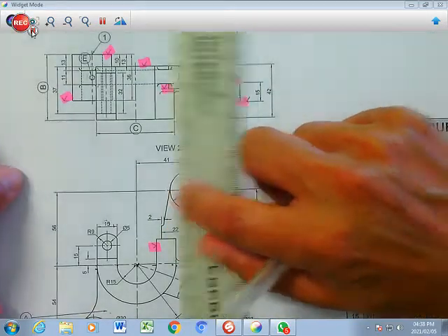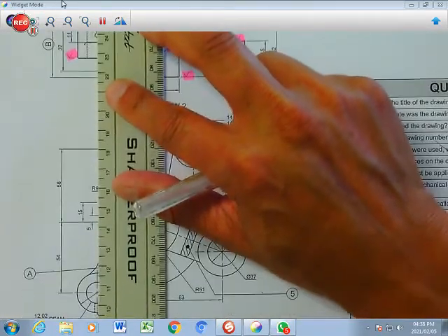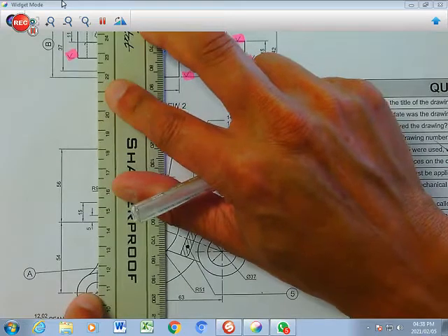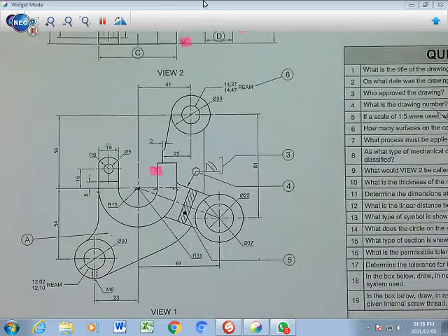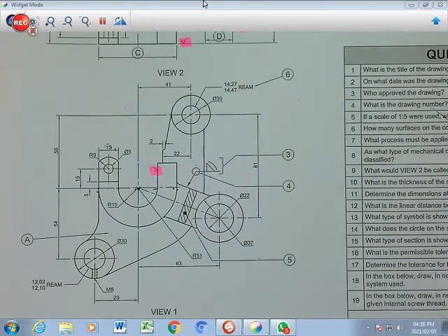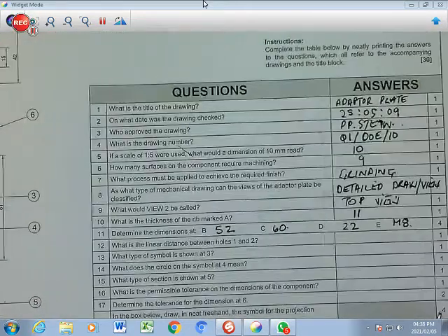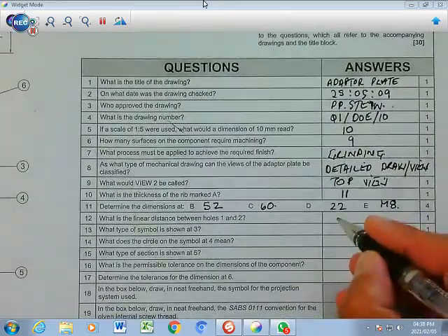And if you go to this center line here, you can find that if you move up, it's in line with that hole center there. So the distance between the two is the sum of the amounts there, which is 23 and 41. And 23 plus 41 is going to give you 64. So we're going to write in the 64 over there.